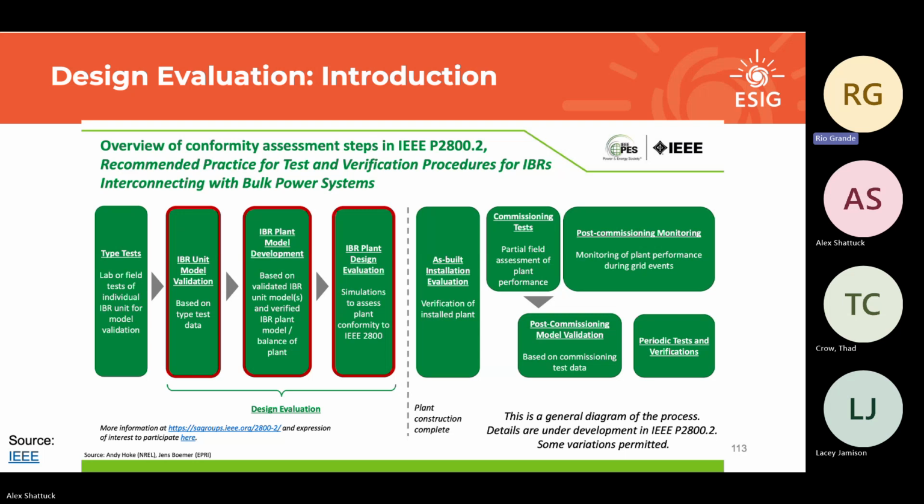So the other piece is commissioning tests, actually testing at commissioning. ERCOT does a good job of this. You're not going to do a fault test at commissioning, but doing a ramp for your reactive power is great. Doing a small voltage set point change is great. Feeding a fake frequency in is a good idea. They're not going to test every single control scheme, right? You're not going to fix everything, but if someone gets one of those 3 easy tests wrong or 4 easy tests wrong, it's a pretty good indicator that the rest of it needs to get some evaluation.